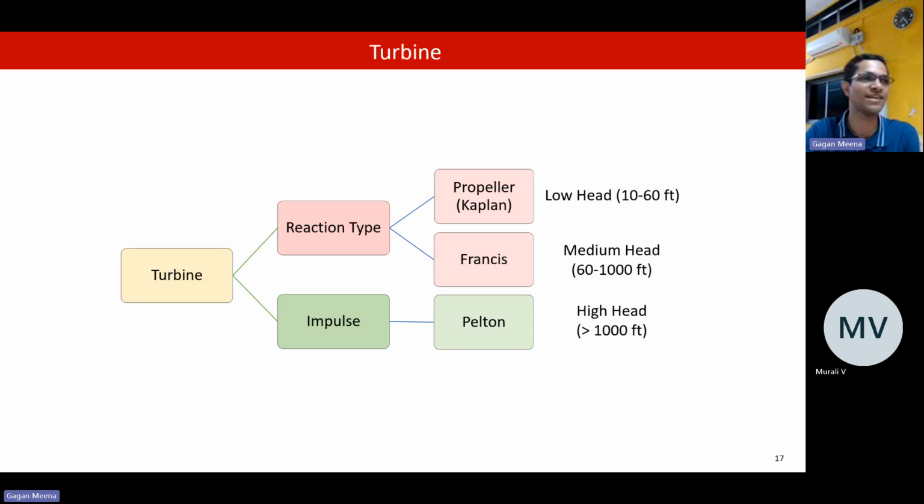So I was saying about Karnataka, right? In Karnataka, they are actually exporting the power only by using renewables: wind, water, and solar. During a few hours, for certain months of the year, they are able to do that. Wind has inertia, and hydro also has inertia. Solar doesn't, but by using inverter control, we can use virtual inertia also. New PV inverters also have that virtual inertia.